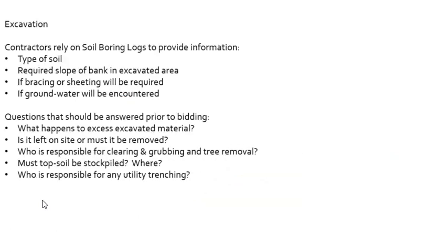All right, excavation. So contractors rely on these boring logs. The geotechnical engineers are the first on the site. They produce the boring logs, and the boring logs are provided by the owner to the contractors that would be bidding on the excavation work.